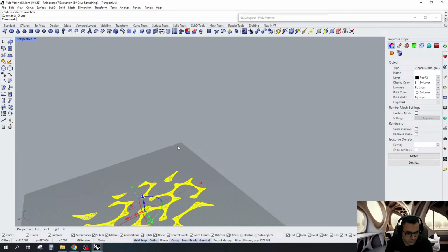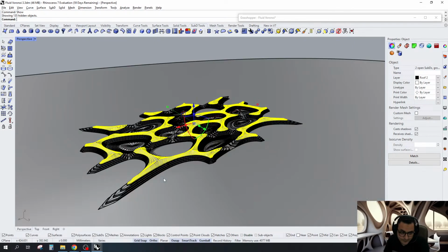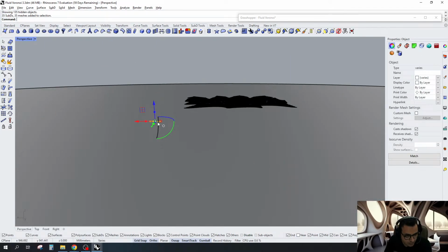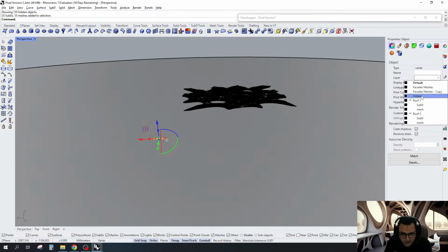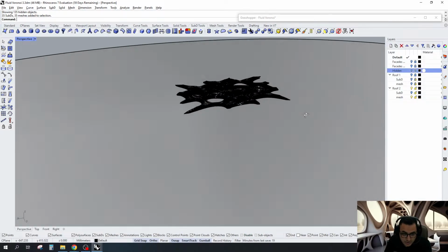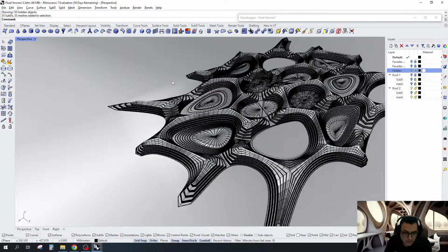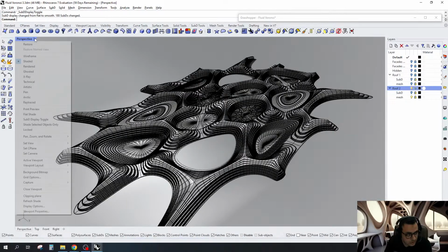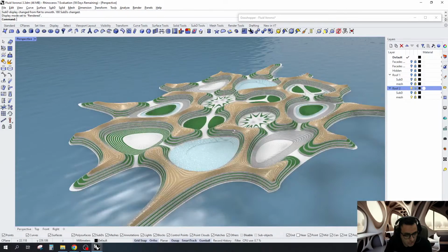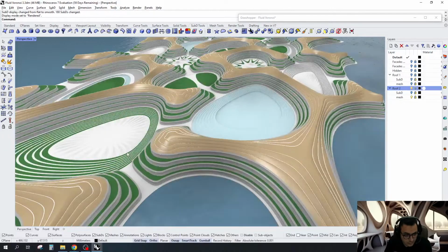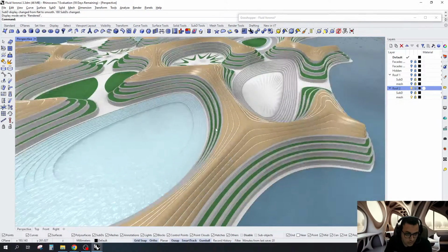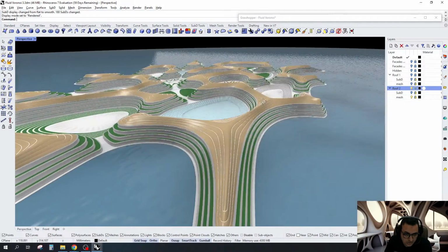So if I set show, by the way, all of these small things, we need to put them on layer hidden and hide layer hidden actually. And roof number 2, let's lock it. So now if you go to here, you can go to the rendered view, and you have the second roof looking, hopefully, so smooth and nice.